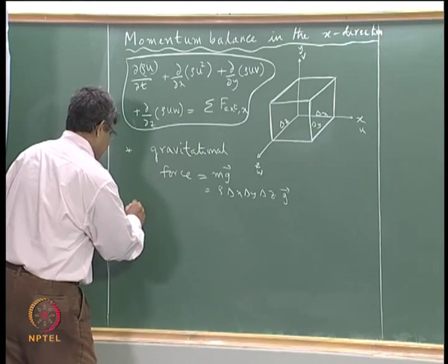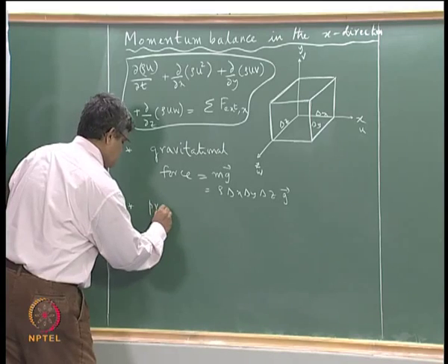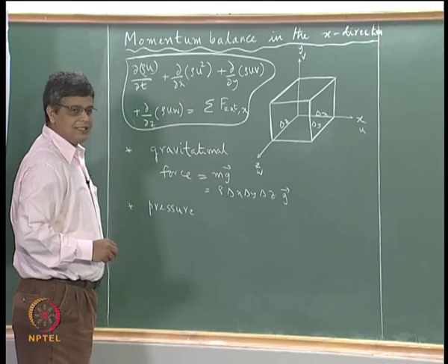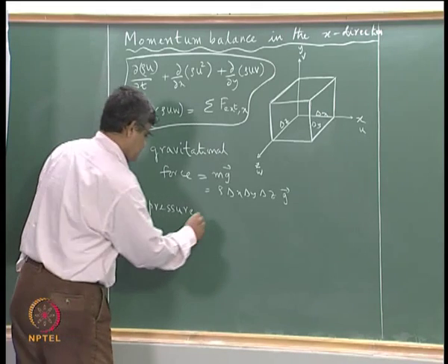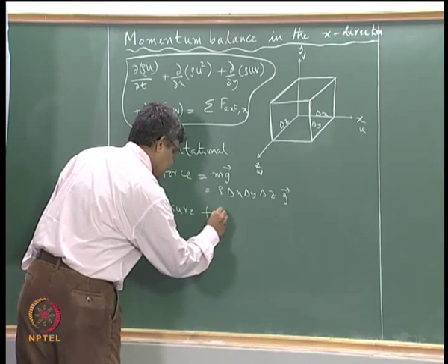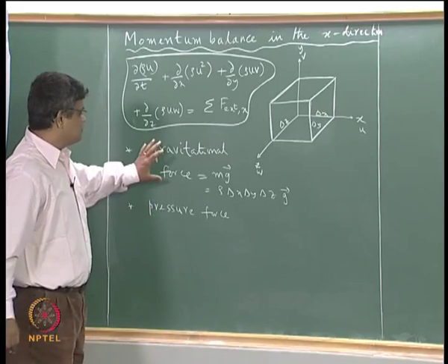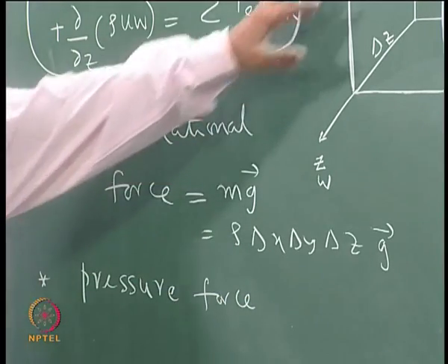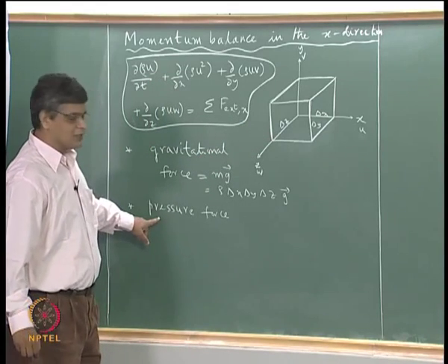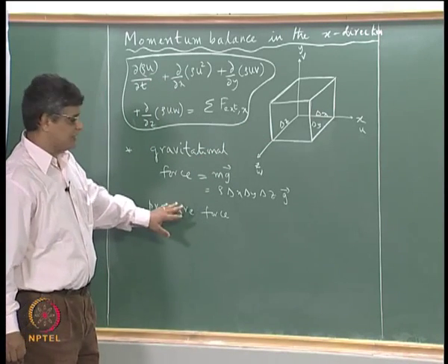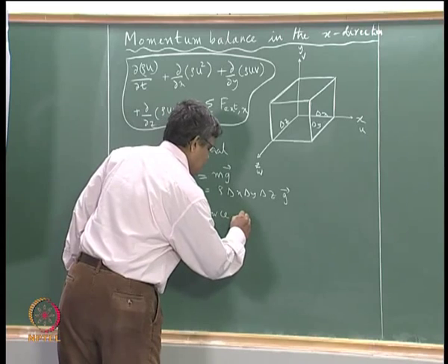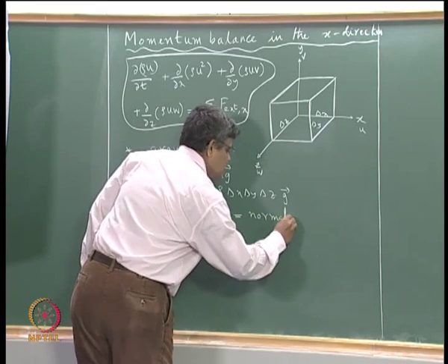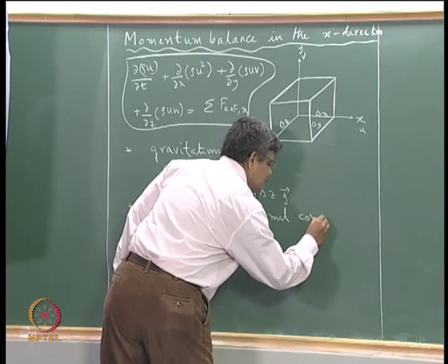We can consider the pressure force, pressure being an inherent property of the fluid. There is a difference between a gravitational force, which is a volumetric force spread throughout the domain, and a pressure force, which is a force exerted on a surface, a normal compressive stress.